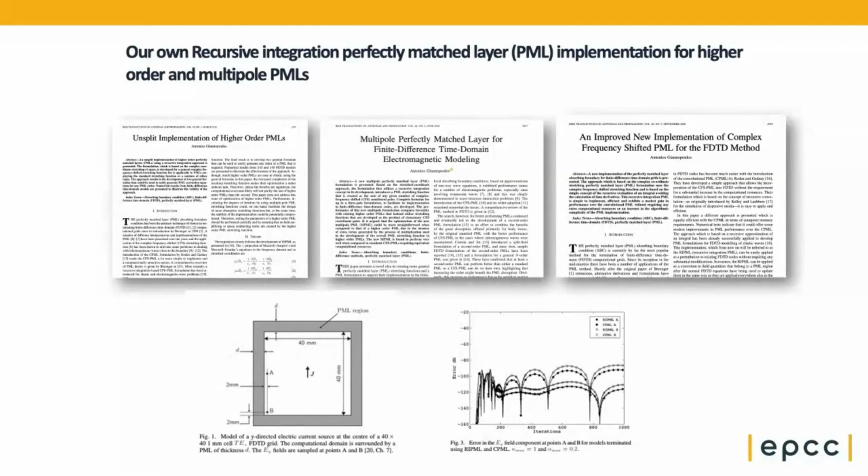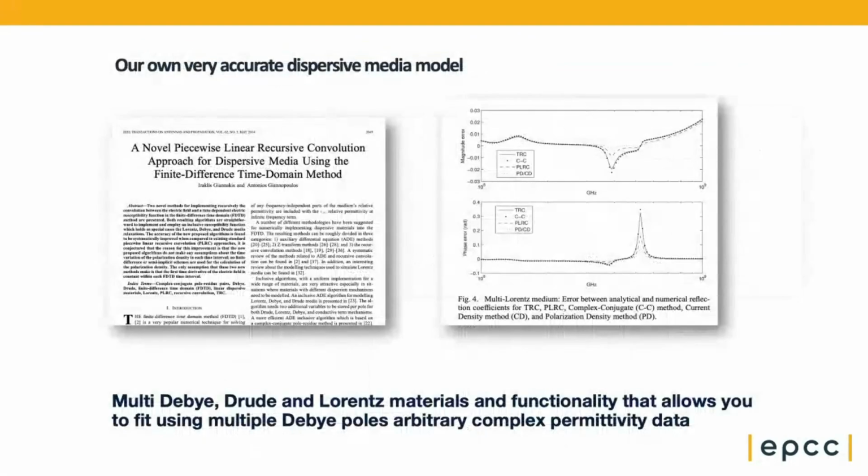We have our own perfectly matched layer boundaries. We have very good boundaries that can be customized and offer very good absorption at the edges of the domain. So when you simulate, as we do, mostly open boundary problems, that means that there is no termination of the wave at the end of the model. We're supposed to model an open space. Then these PMLs, these perfectly matched layers, are our own formulation, and can be customized, and they have very good performance with very small errors, even when the sources or the scatterers are close to them. So we're very proud of this kind of work.